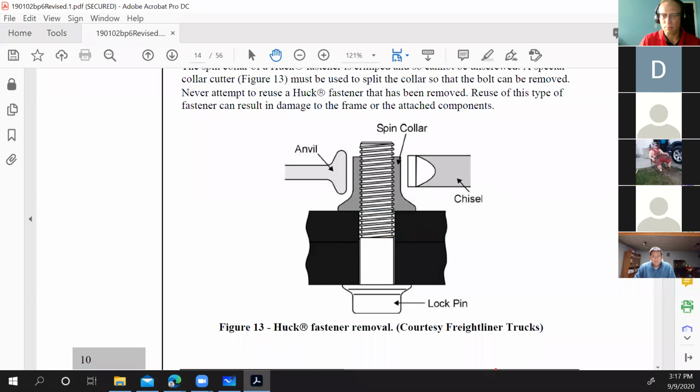Yeah, that might be the brand, but essentially it's just a different stinger that goes on your stick welding machine, and that has an air outlet on it, and then it takes a special rod that instead of being weld with flux, it's carbon, and it just makes intense heat. Like you have to turn your welding machine all the way up, essentially, and it uses that really high amperage to burn the steel away.